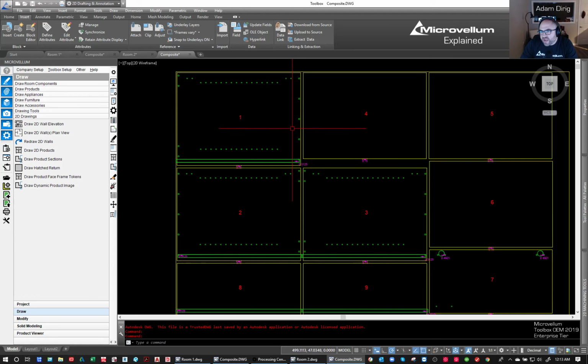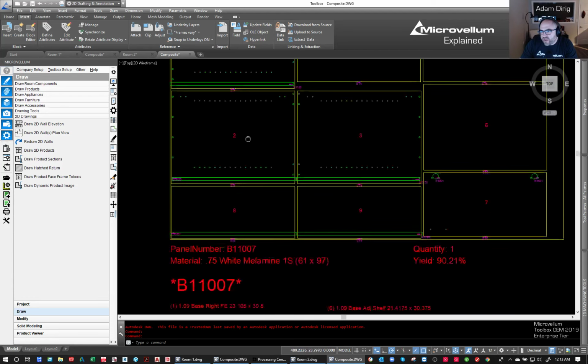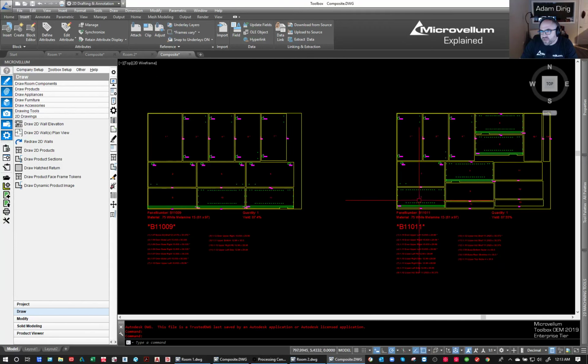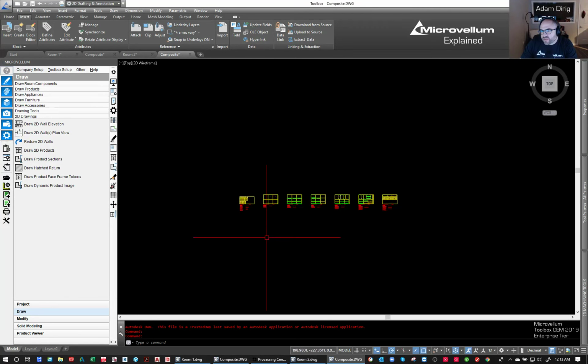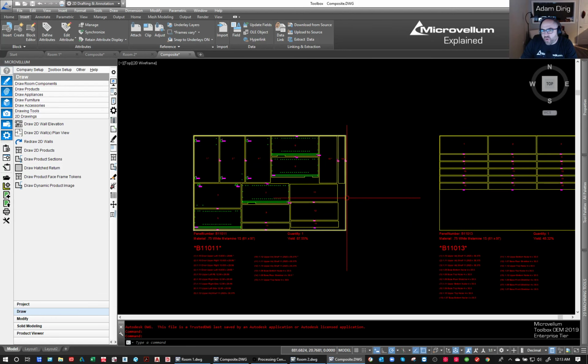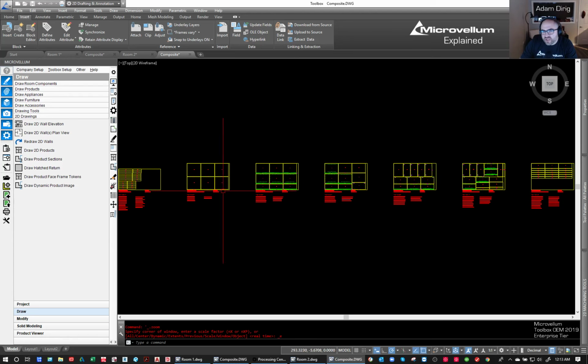Everything's nested. Everything's got a number associated with it, and then it's just organized down here. It's a great way to look at things. So we can just see how everything's going, and if we need to tweak stuff or change stuff or add, we can edit this nest however we want and then just update the G code from there.